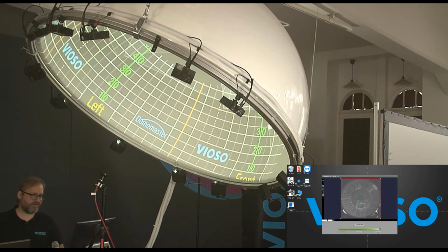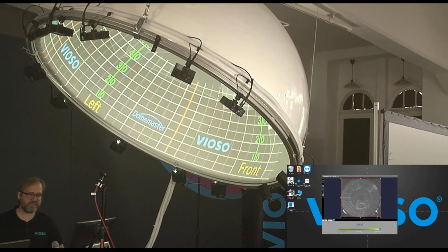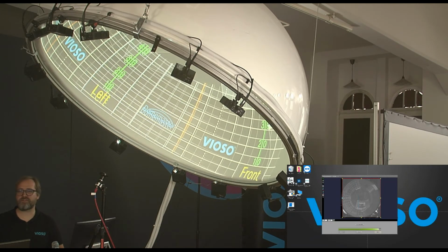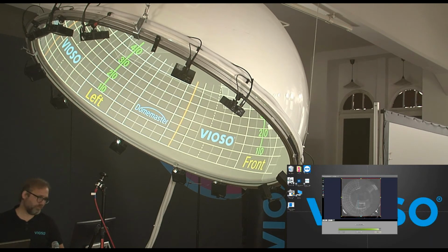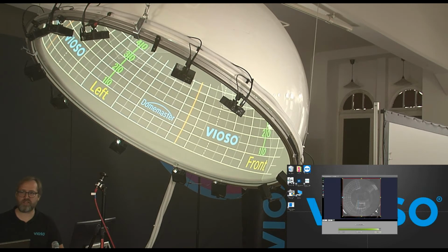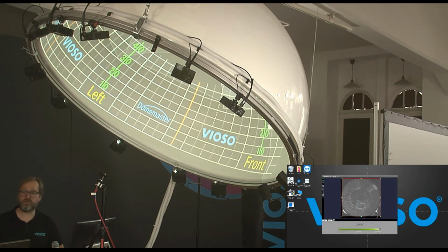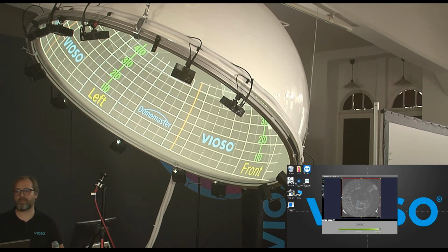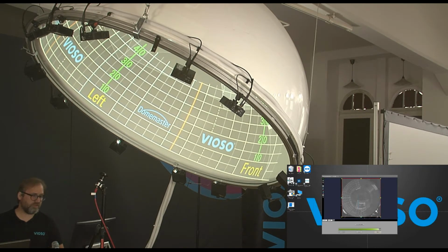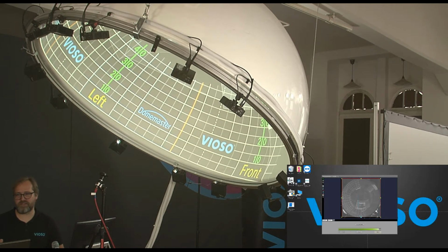After the scan, we see now already the result. This is the alignment that you can see. After the scan, I can work on this alignment in real time and modify it, let's say to match, in this case, with the shape of the dome. Since we don't know where the dome is, and there are no markers or something attached, we simply match this manually, which is quite an easy job to do for an operator, since we do not handle each projector individually, but simply edit the whole result of it.